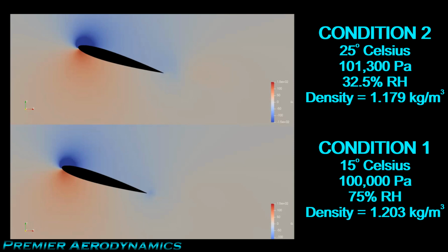So you would do your experiments, and then you want to normalize or non-dimensionalize these two forces that you measure, which will be different, by the way, because the velocity is higher for the top one than the bottom one. But you get these forces, and you're under the assumption that both of these runs were at 15 meters per second.